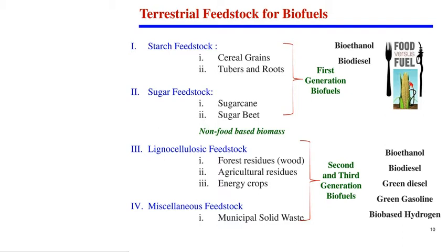Let me go to the next slide now. If you want to make biofuels from this kind of material, what are the challenges? You see the challenges here in the truck itself. It can be leaves, twigs, which means very bulky, low density, or it can be woody material, slightly higher density. It can be in chips or round wood. So, what are the major challenges? Low bulk density. In the truck, we want to carry energy, not the water or this air, because it has low bulk density and high moisture content.